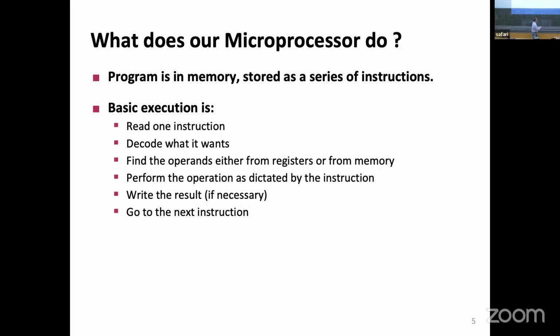And I have my result, and now I know that this result will go back either to memory or register. If it's an R-type, it should go back to the register. Where do I find where it goes back? There is a third address here, and the write data. So the data comes back, and the address comes again directly from the instruction. So this completes the cycle.